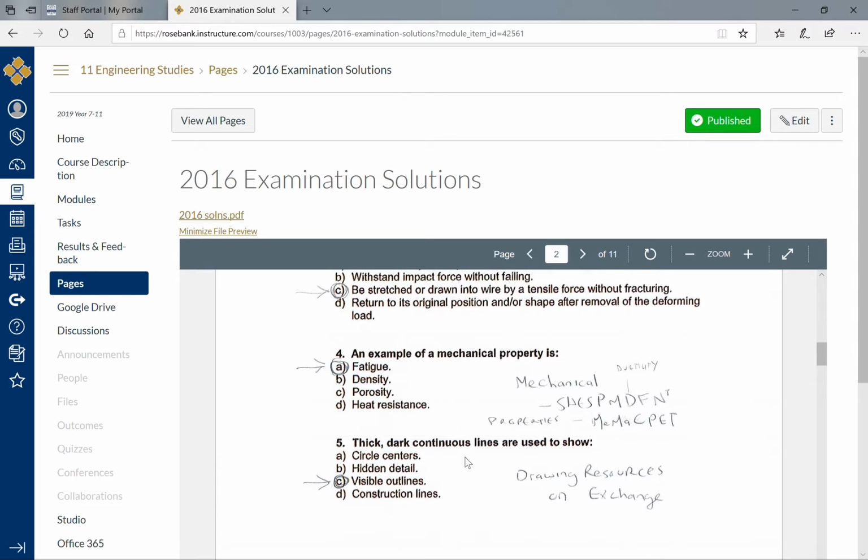We discussed this when we were talking about materials, and we talked about two little ways of remembering all the mechanical properties. And I use this little thing here. She's PM, she's the Prime Minister, defend the Northern Territory. So this comes out to, and you need to remember this, strength, hardness, elasticity, stiffness, plasticity, malleability, ductility, fatigue, and the NT, because little subscript T is notch toughness. So you need to remember that and what each one of those actually means. And you want to study that.